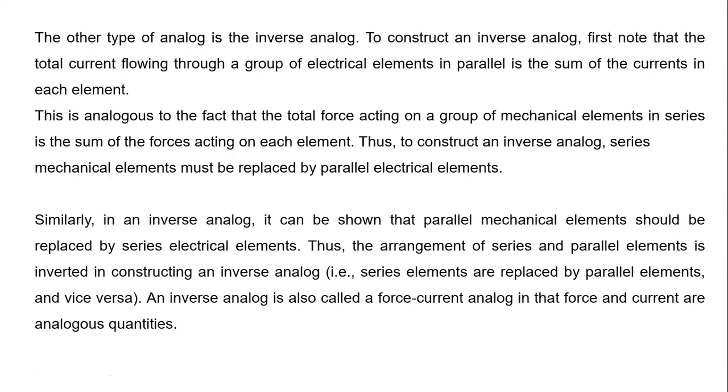Similarly, in an inverse analog, it can be shown that parallel mechanical elements should be replaced by series electrical elements. Thus, the arrangement of series and parallel elements is inverted in constructing an inverse analog.